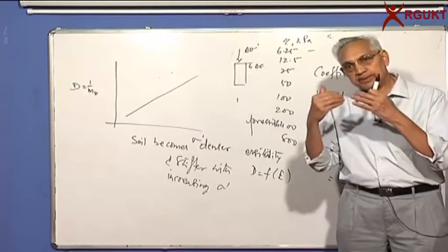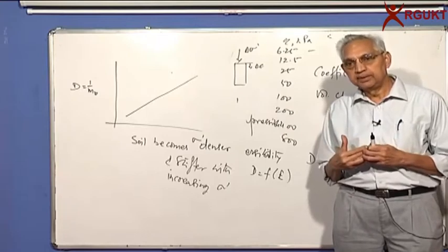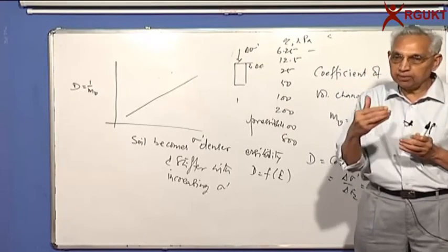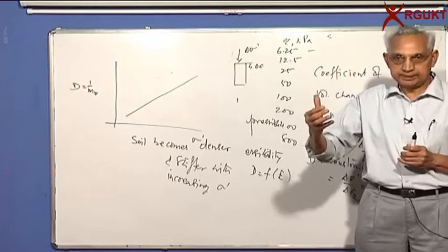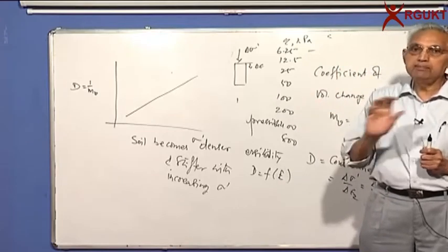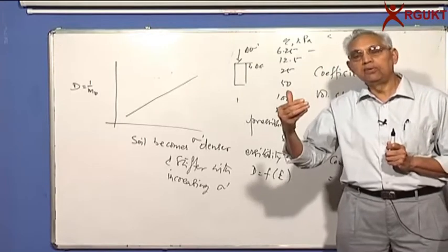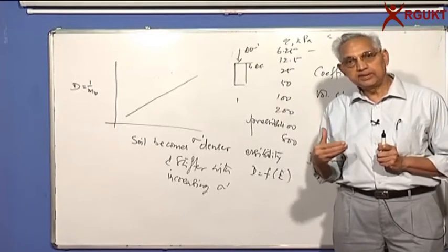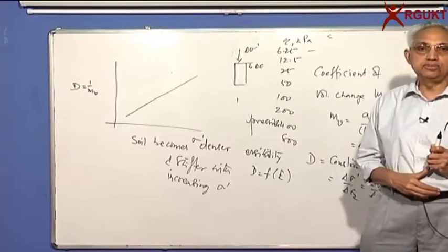If you now go for the second floor, for the same increment in stress, the settlement will be lesser than what it is under the first increment. Suppose you go to the third story and increase again by 10 kPa, the settlement due to the third floor will be less than that due to the second floor, which again is less than that due to the first floor.